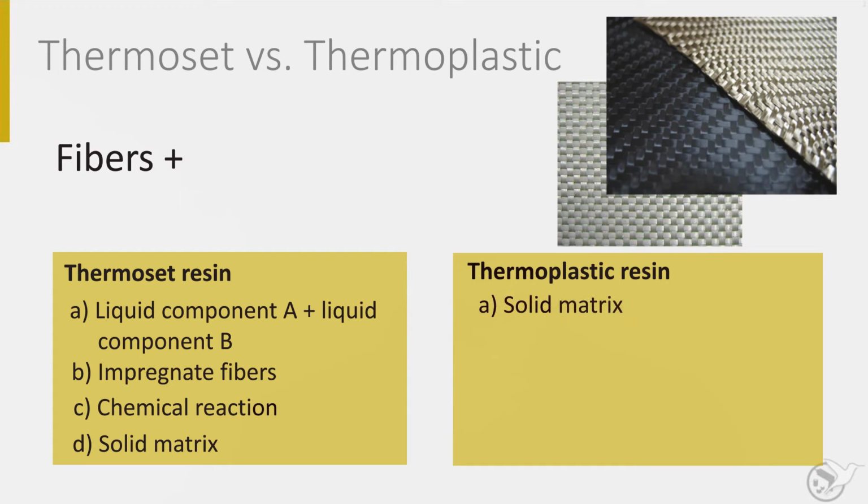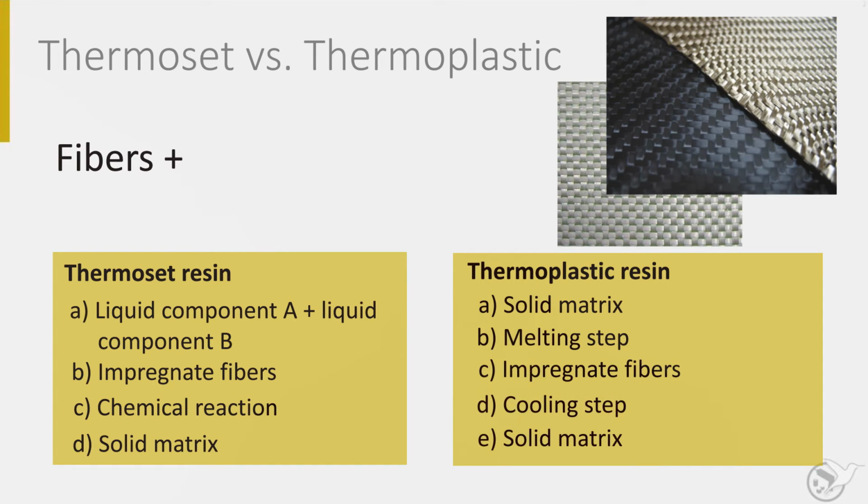Thermoplastics are solid at room temperature and don't react chemically. The long molecules in the substance can be disconnected by heating the polymer. At that temperature, the polymer and the fibers are mixed. Since the viscosity of the thermoplast remains high, different methods are invented to get proper impregnation of the fibers. Examples are using a solvent in the polymer to lower the viscosity, mingling the fibers with thermoplastic powder, and using polymer fibers mingled with the real reinforcing fibers.